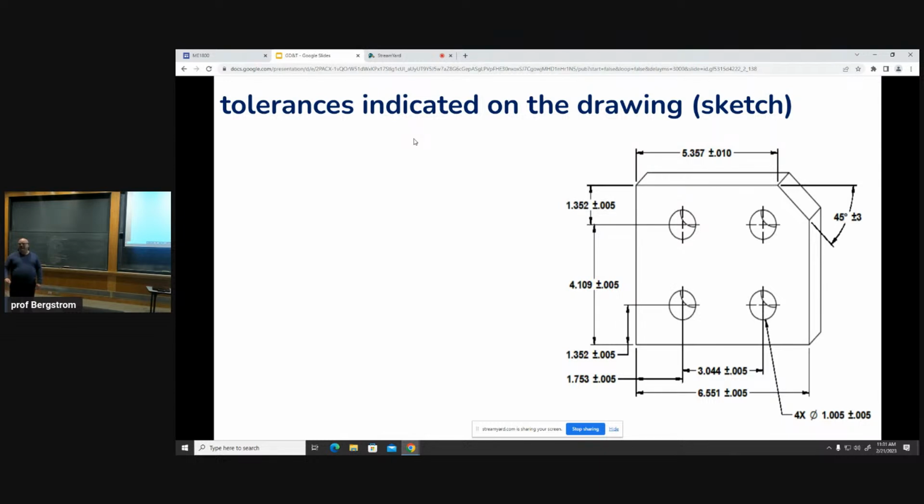Like those skinny girl martinis, right? The skinny vise. Yeah, so if it was a larger piece than your vise jaws, and you could get a skinny vise that could do this, you could have a tool path, and so I might orient it the other way. I'm not going to change the board orientation here. Right, but if we would hang it out both edges of a vise, then we could have a program that does a contour on one side and a contour on the other side.